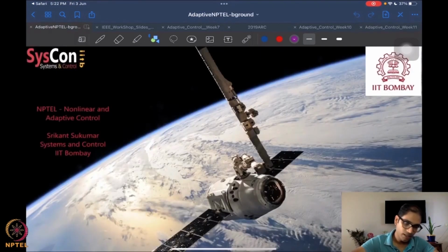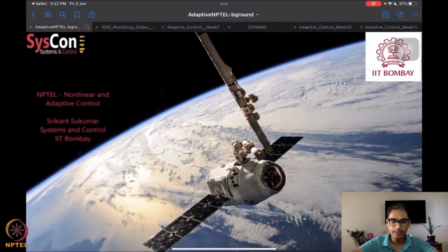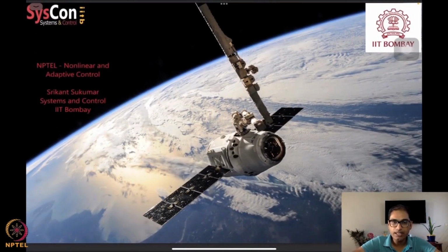All right, excellent. So what did we look at in this session? We started this week 10 lecture with a discussion of robustness in adaptive control. We've not really looked at the adaptive control problem at all, but we took a very simple scalar system and tried to understand what disturbance analysis looks like and what the notion of residual sets is, and the fact that trajectories starting outside the residual set will converge to inside the residual set if you had a strict Lyapunov function.